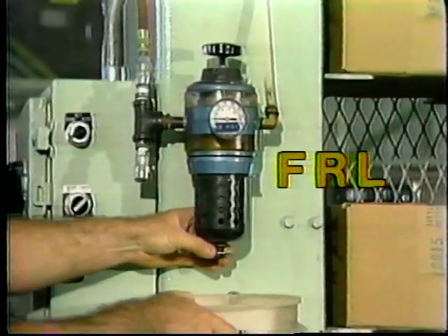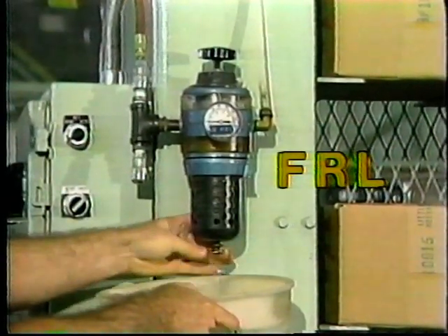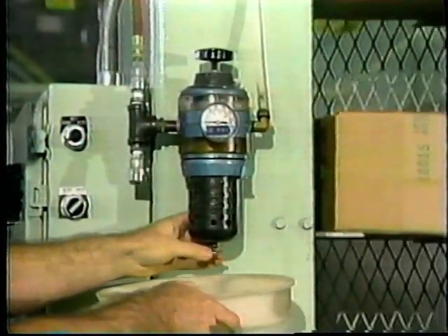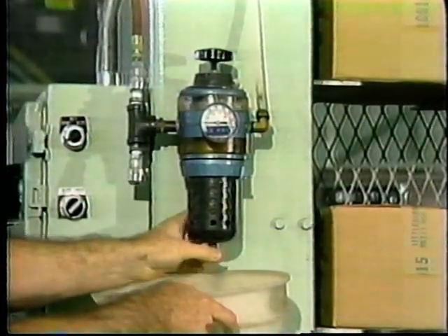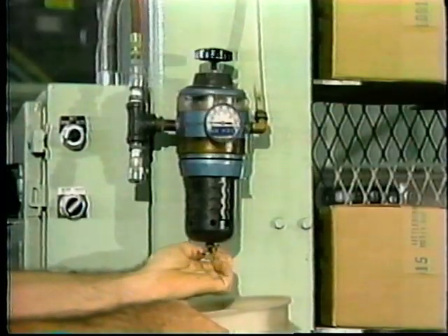Here are some tips when you're using FRL units. First, make sure they are sized properly and will provide the maximum required flow rate for the part of the circuit they are supplying. They should be placed as close as possible to the point of work and accessible so you can easily perform periodic maintenance tasks such as filling, adjusting, and cleaning.